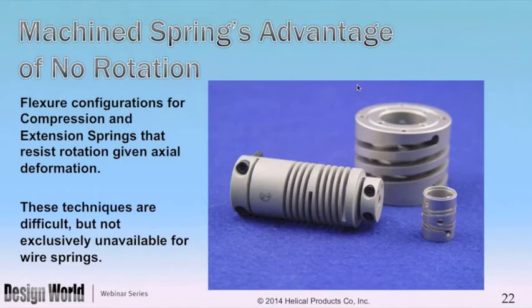And I should say also what happens here is in the middle, where the flexures are just apart from each other, that's where you actually get the motion, but the ends do not. There's also a problem with wire in this sense that you may end up having some moments, and the center part may be buckling out a little bit when compressed.